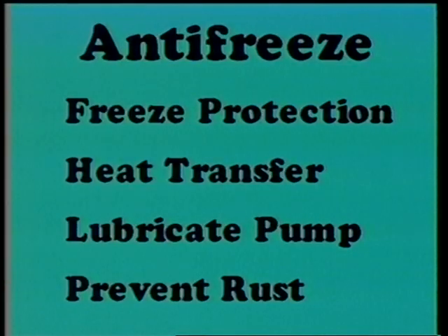Antifreeze is very important to the proper functioning of a cooling system. It provides freeze-up protection in cold weather, better heat transfer than water. It also lubricates the water pump, and it prevents rust formation in the system much better than pure water. Ideally, a 50% mixture of antifreeze and water should be used.